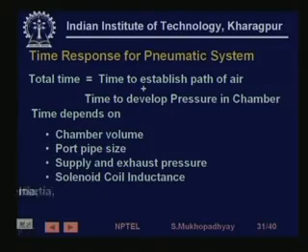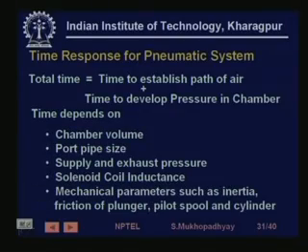These times depend on a lot of factors like chamber volume, port and pipe size, supply and exhaust pressures, that is the ratio of the upstream and the downstream pressures. Similarly, there are also times required for the solenoid, coil inductance, inertia, etc. They are generally smaller compared to the pneumatic part, but all these factors will affect the time response of a pneumatic system.